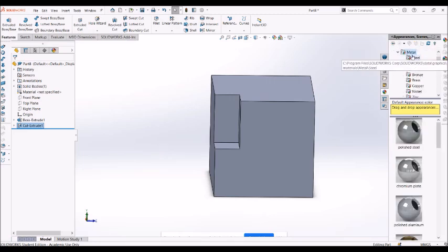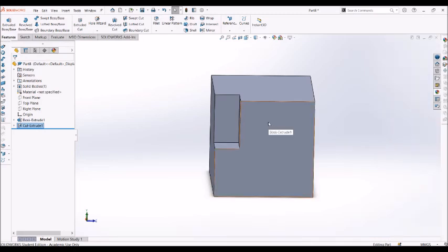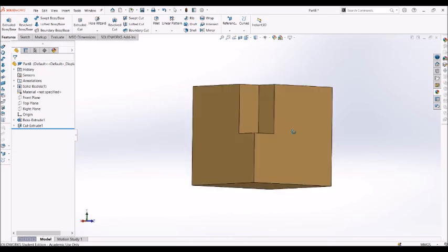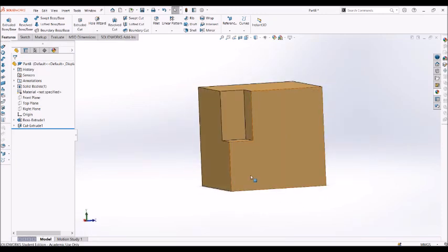So I click on metal and it brings down this little drop down menu. What type of metal do I want it to be? Well, maybe I want it to be gold. So if I click on gold, I click on the material and drag it over. I can apply that to the whole body. To do that, you make sure you click the one that says body. And that means that cube is now made of gold.